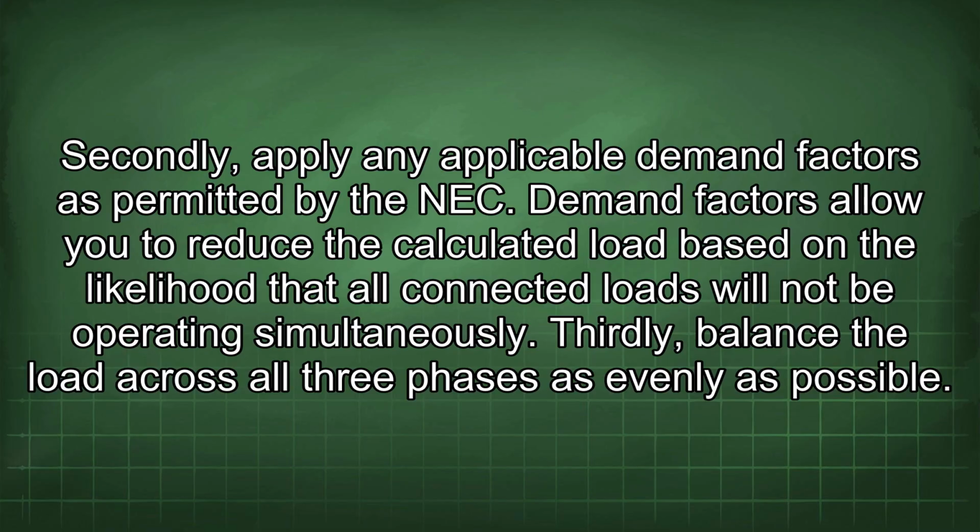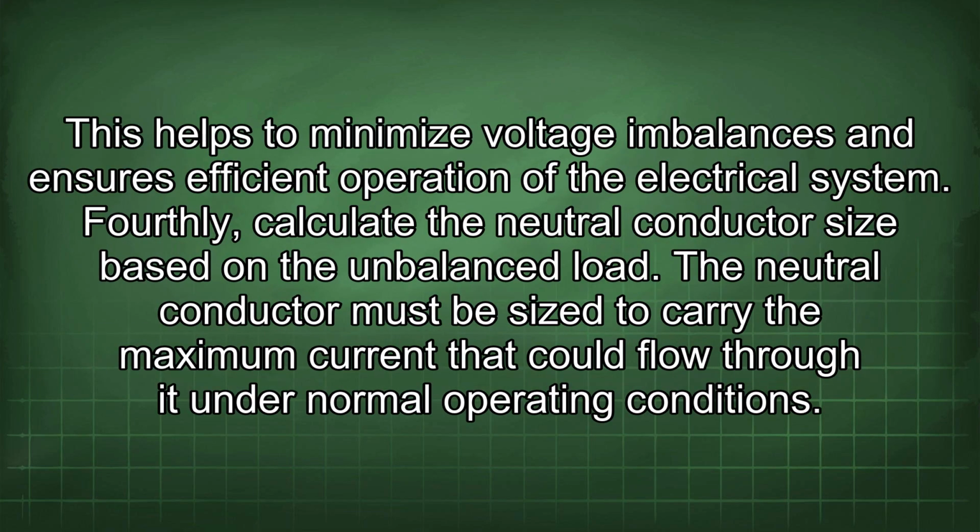Demand factors allow you to reduce the calculated load based on the likelihood that all connected loads will not be operating simultaneously. Thirdly, balance the load across all three phases as evenly as possible. This helps to minimize voltage imbalances and ensures efficient operation of the electrical system.